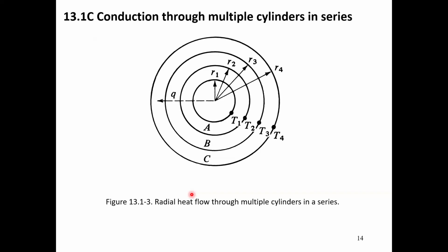you don't want thermal energy to be lost as we move from one utility section to another, to the main plant and so on. So what we do is we add an insulation layer. For example, A could be your metallic pipe carrying steam, on top of which you add a layer of insulation, and on top of which you add another layer to hold the insulation together. That's a typical example.